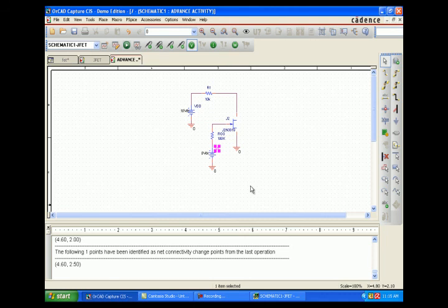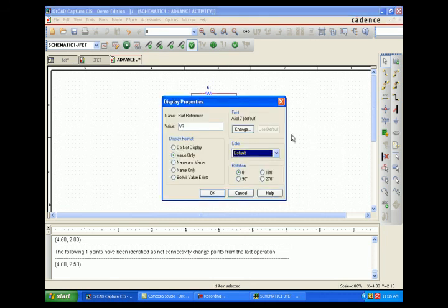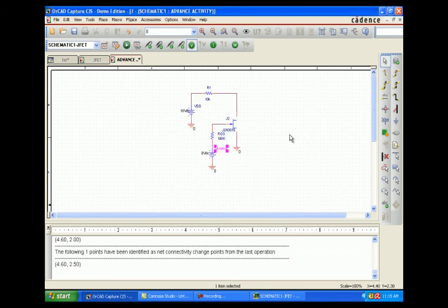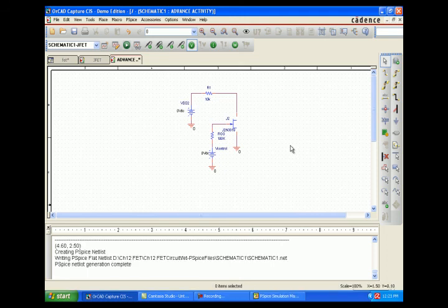Now we want to have a V control. This will be the V control voltage of 2 volts, but we have a variable list of minus 2.5, 2.8, 2.9, 2.94. So this will be the controlling voltage we give as a parameter in the simulation so that we can trace the family of curves.